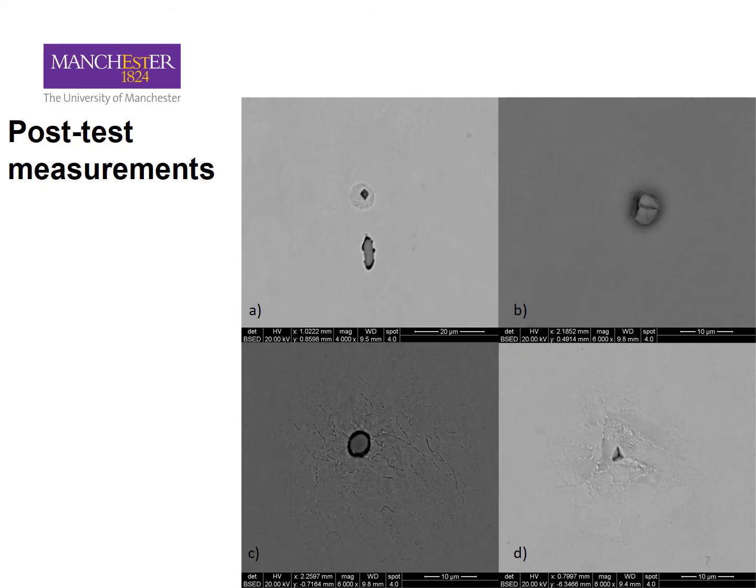Some example images are shown on this slide. What we see here is the normal metal matrix of the material. This point is a particle. At the top and bottom of the particle, the black regions are where the particle has decohered from the matrix, so a small void has formed here, no loads being exchanged, but the particle is still attached around this point.